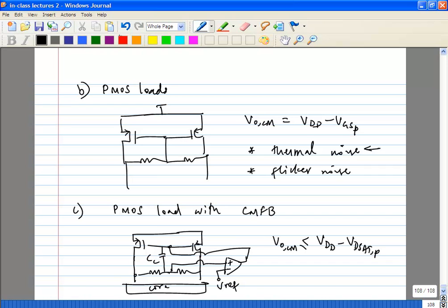Okay, up conversion mixers, we know we have a tuned load. So let's say we down convert to IF, and if the IF is large enough, you don't worry about flicker noise, because the flicker noise is going to be around baseband. If your IF is small, or let's say you're looking at a homodyne or direct conversion receiver, I think we briefly looked at it last time, where the IF frequency is 0, for those receivers the 1 over f noise will definitely matter.